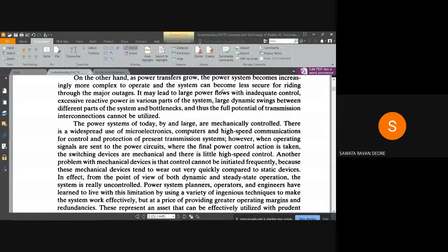You all might know that if we talk about a switch, the life of that switch is not counted in terms of years. It is not 10 years, 20 years, 30 years; it is counted in terms of number of operations. Like this switch has 5,000 operations, like this switch has a life of 10,000 operations, meaning 10,000 turn on and off it can sustain.